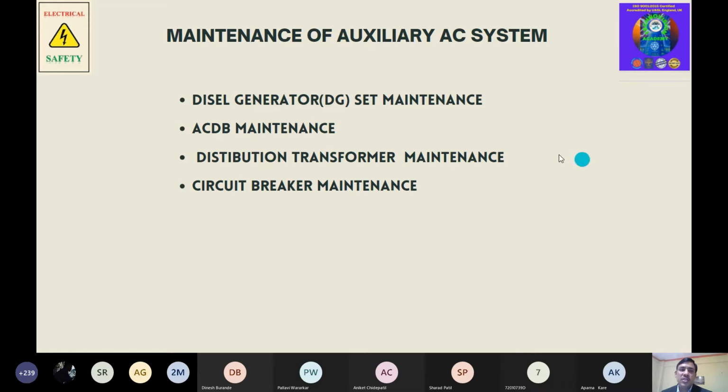My first advice to all of you is to work with safety, because life is most important. So safety precautions should be taken while working on any EHV station. It might be your low voltage side, or a distribution voltage of 220. Suppose it is a very low voltage, what can happen? But many things can happen, even only some milliamps of current is required for death.